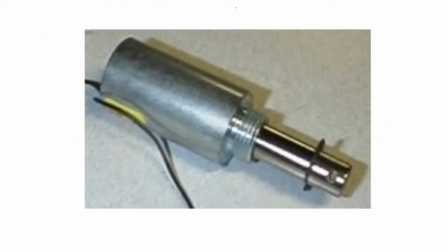This is the plunger which will come out and go in after you have an electrical connection, and this is the wire which will have your electrical connection. So depending upon the electrical connection, the coils inside will get induced with voltage and current starts flowing, and because of that, the magnetic lines of force will make the plunger come in or go out.